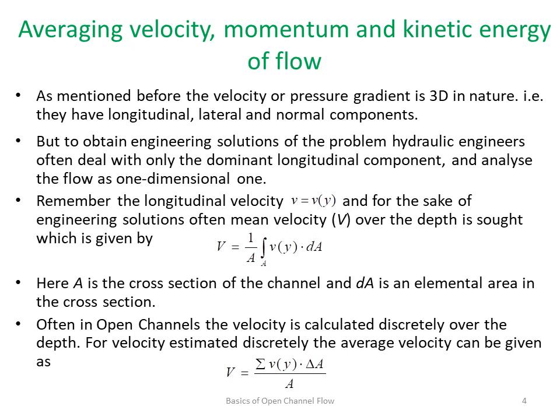As we mentioned before, the longitudinal component is the dominant component which we often focus on. Moreover, engineers actually focus more on the depth average mean velocity in the longitudinal direction. So the actual longitudinal velocity, which is given by small v here, is a function of the depth, or a function of y here, as it is shown.